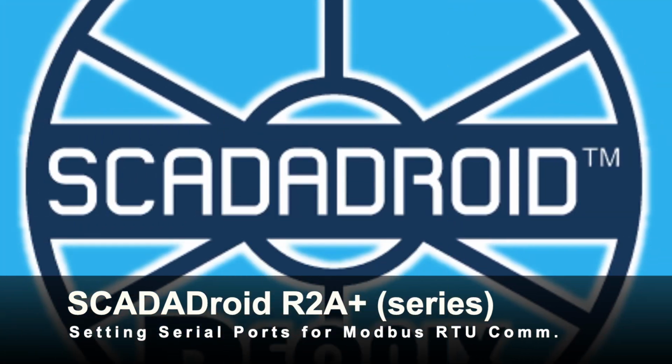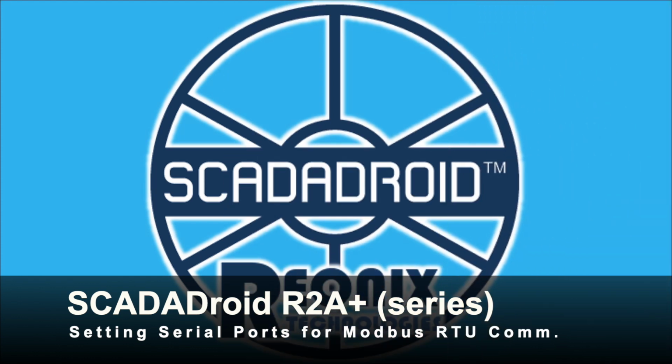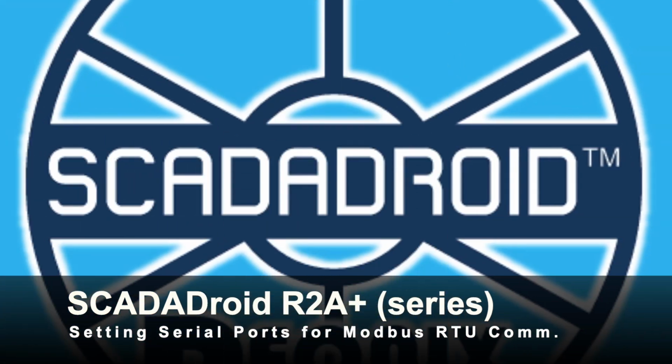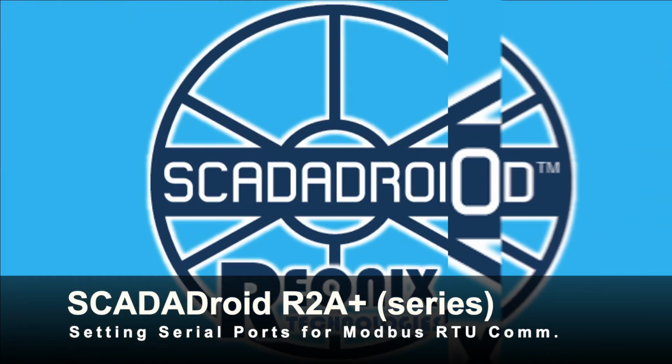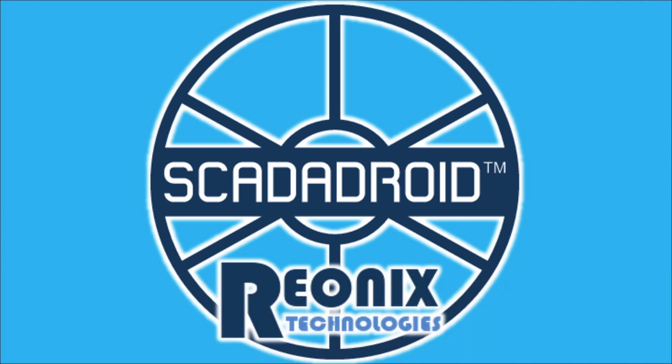2. RS485 serial ports can go over 4,000 feet, and therefore, devices can communicate at a further distance and on a cheaper cable than using either fiber optics or Ethernet with repeaters to get the distance, albeit at a slower rate. And 3. Serial ports are much cheaper to develop and less complicated from a manufacturing perspective. Because of this, many manufacturers use them for digital communications.